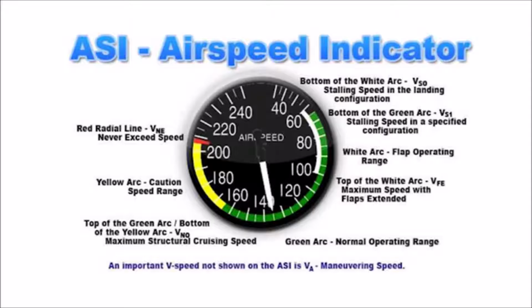In order to maximize efficiency and quicken communication in the cockpit, significant performance-related airspeed values are abbreviated and referred to during the phases of flight. These abbreviations all begin with the letter V, referencing velocity. VA is the abbreviation for maneuvering speed. Maneuvering speed is the maximum speed at which full or abrupt control movements may be used without overstressing the airframe.